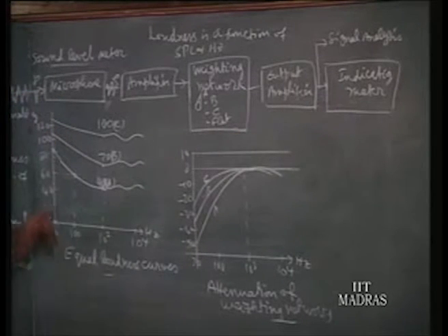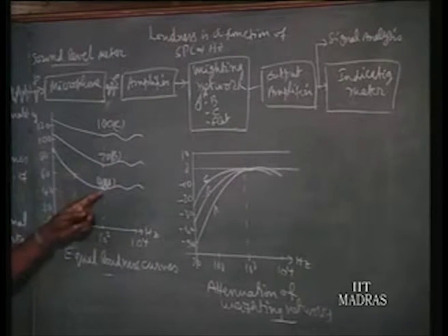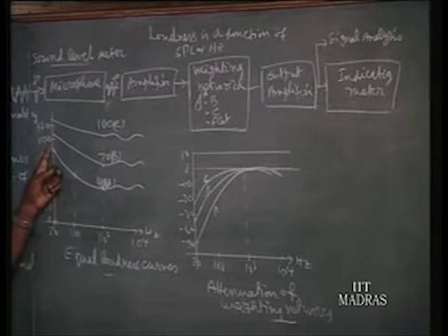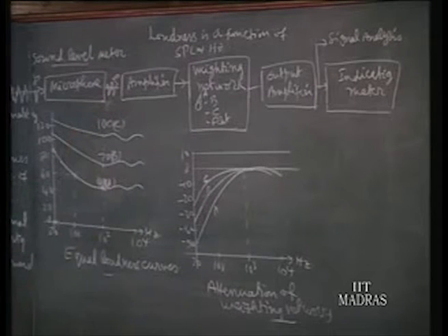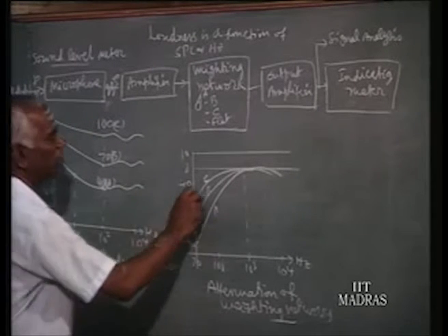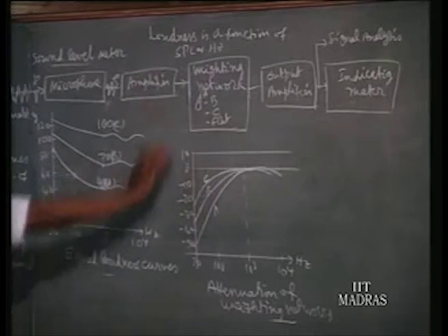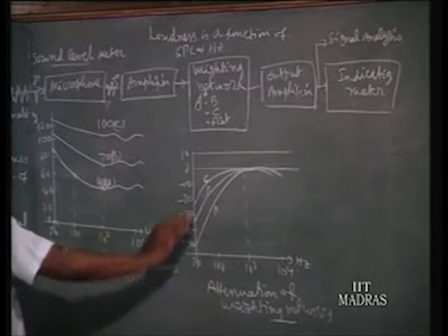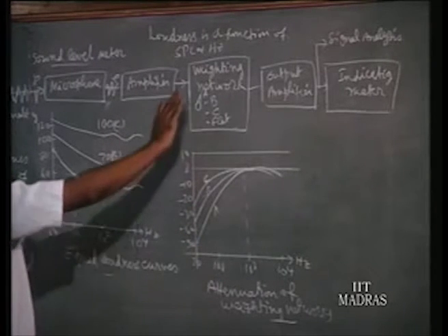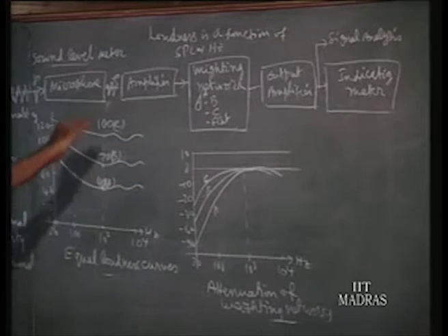That means if it is 90 decibel at 20 hertz, our meter will show only 40 decibel. It is because the loudness of 90 decibel is equal to the loudness of 40 decibel at 1000 hertz. So it will show 40. Similarly, for A, B and C weighting, what they will subtract for a given frequency is given here. That is this electronic network, what we have under the weighting network. This electronic unit will sense the frequency, accordingly subtract the value, and the remaining value goes further.